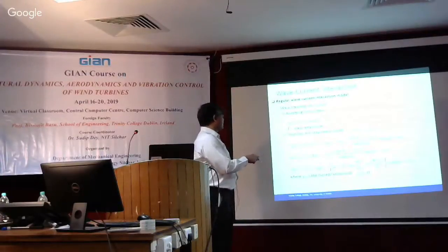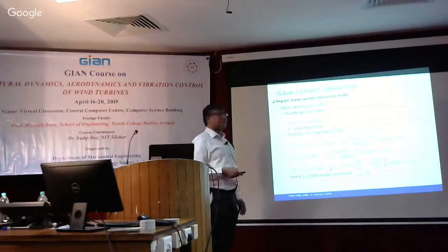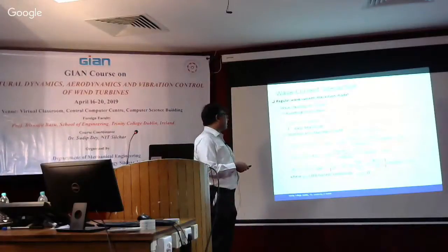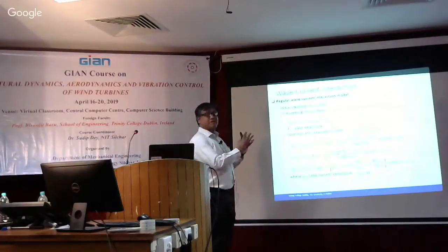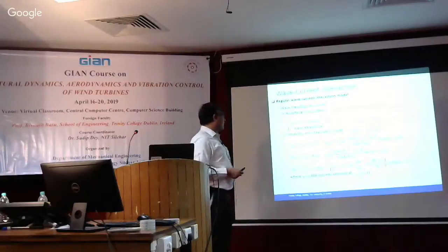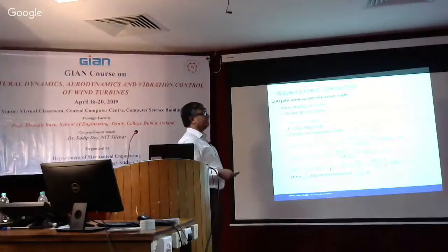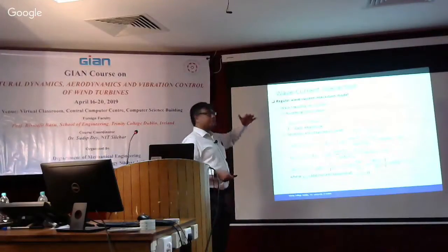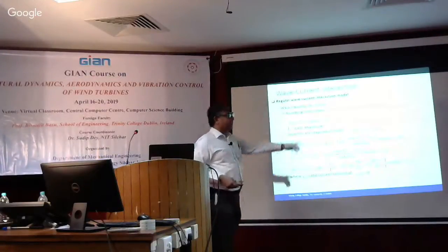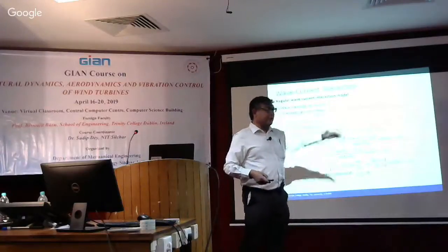So you can see that now the amplitude is actually being affected because of the presence of this u0 of the current. So what we've assumed is that u0 is the current which is propagating under the wave, and that actually impacts the response of the fluid. So here u0 is the current velocity at z equal to 0. So z equal to 0 is at the top surface. So obviously the profile is nonlinear, but u0 is the value at the top.